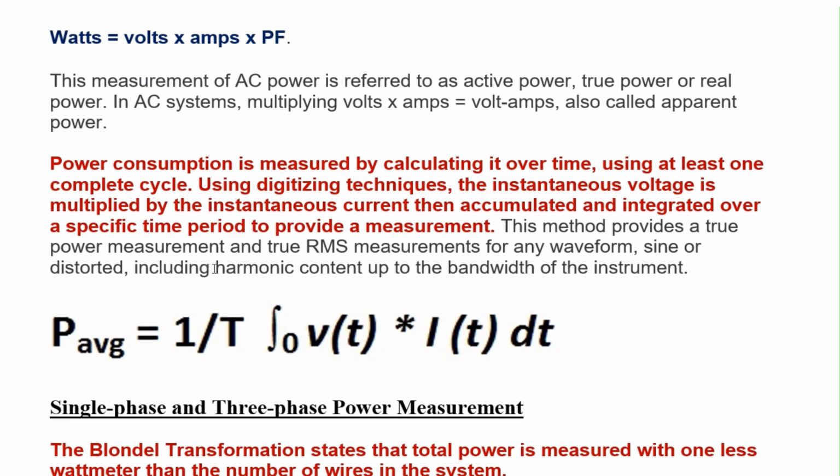Power consumption is basically measured over a period of time. Basically, in the instruments, it is measured over one cycle. So by averaging the power consumption of the one complete cycle, the instrument can predict how much power consumption is taking place in the circuit. So this is achieved over the time. It keeps on measuring that by the sampling method.